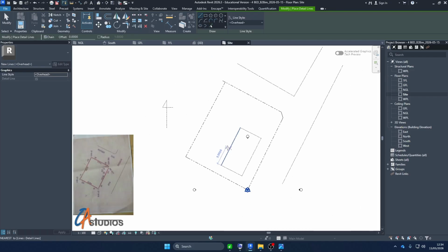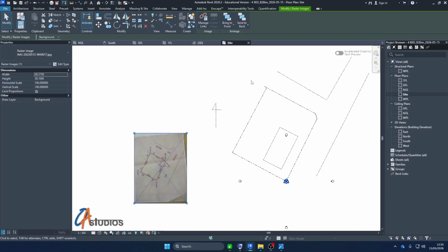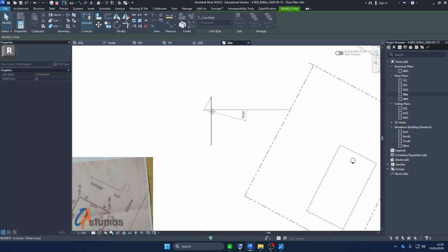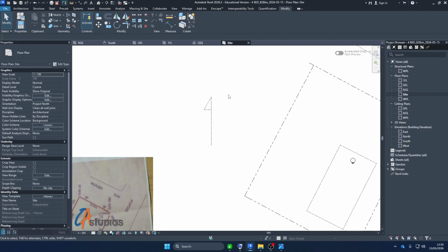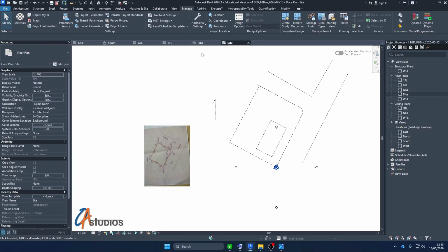So to do that, we would have to make our site, so usually in the site view the north arrow is straight on the site regardless of the inclination. Leave your north arrow straight, but on your floor plan the north arrow can change, but make sure the floor plan is straight. And to do that, there is something you can do in Revit under the Manage tab. It's called rotating your coordinates, per se.